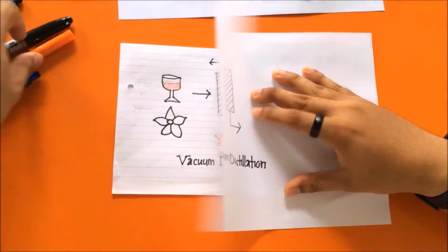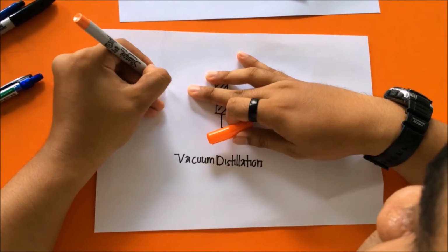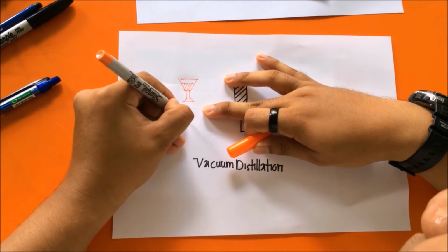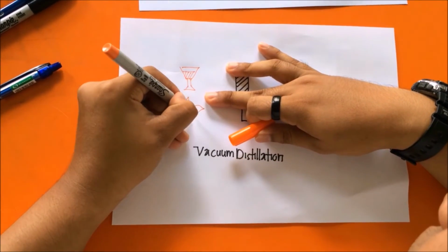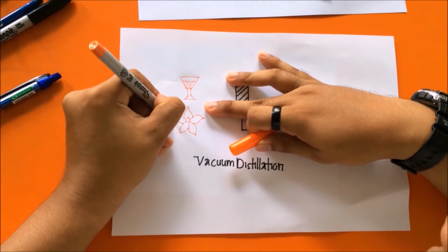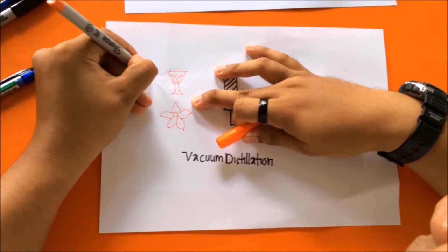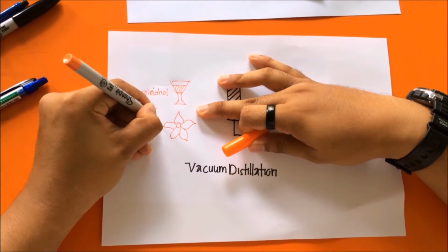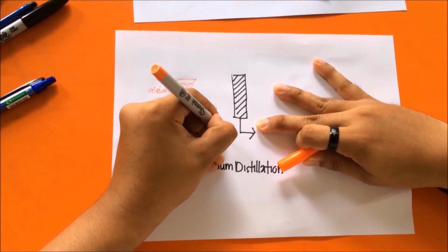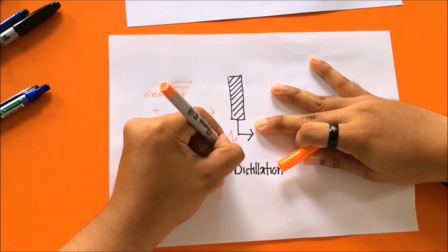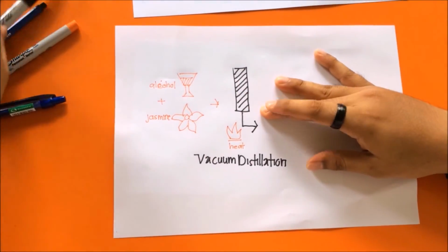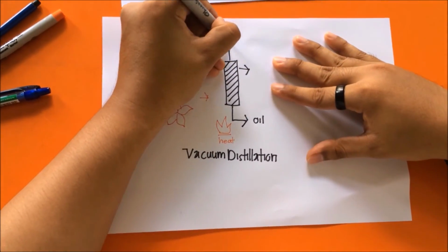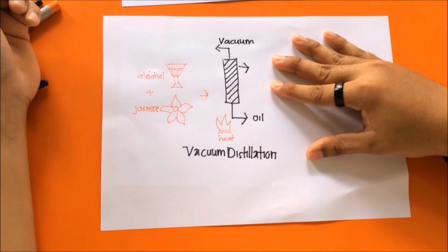When using a distillation column, the column design should allow for effective separation without it being liable to flooding. An undersized column will be liable to flooding, which may result in high pressure and therefore high temperature in the still. Flooding will also affect separation and can result in downstream problems such as water-solvent separation in reactive distillations. Compatibility of materials of construction is particularly important as there is an increased surface area in column packing. Corrosion products from the column packing may catalyze decomposition or reaction in the column.